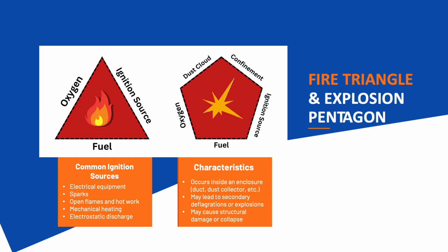So really, what are the risk factors here? There's kind of two risks we're talking about. On one hand is fire risk. On the other hand is explosion risk. So to start a fire, what you really need is three components. You need a fuel, so a combustible dust in our case here. You need oxygen that could be provided by airflow through a ductwork, mixing with your dust or settling with your dust. And you need an ignition source. So that could be a spark generated by a grinding process. It could be some kind of an open flame if you're cutting or welding. It could be a spark generated by a material handling fan. So anything could generate a spark, combined with oxygen and fuel, you get a fire.